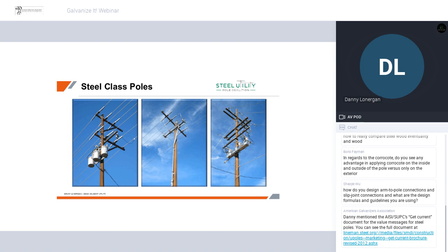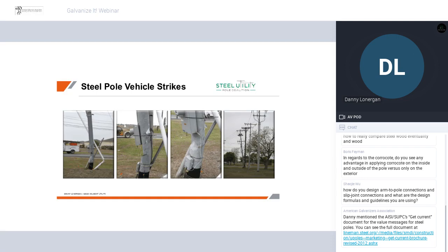So a utility has chosen or knows they have to mount a lot of equipment on a given structure. And typically this equipment's very, very important. All things being even, it's pretty expensive in relation to the pole itself. So often we find non-wood poles, engineered materials, finding their space in "equipment pole" structures.